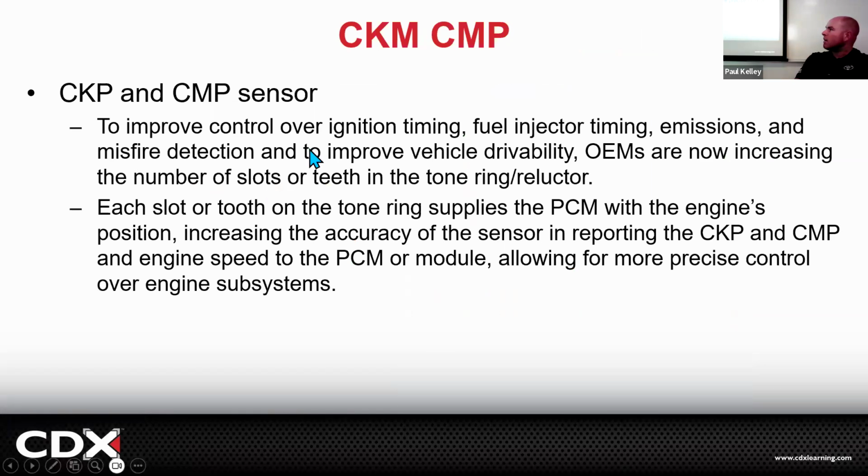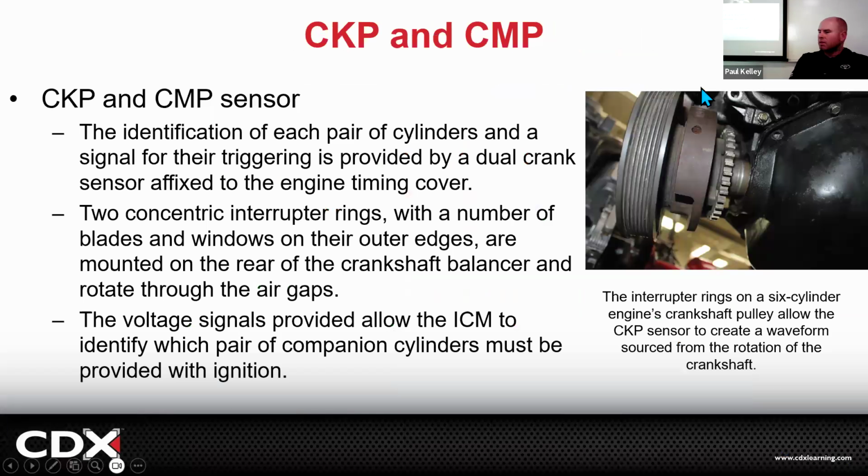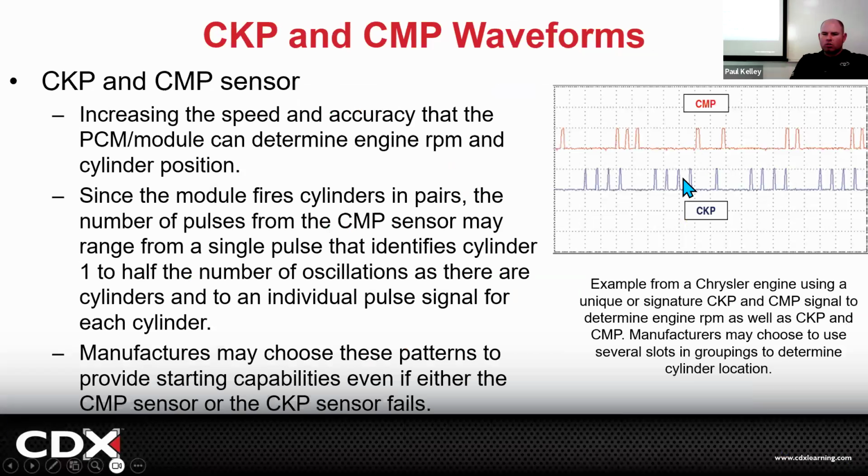And then again, the crank and cam are inputs to the timing, but they also end up being the tattletales if there's a misfire, okay? And then again, you can see them, like this one's a crankshaft position sensor. So we got a sensor that's reading each of these teeth. Cool. And what we would do is graph that out, and we could look at camshaft pulses and crankshaft pulses.